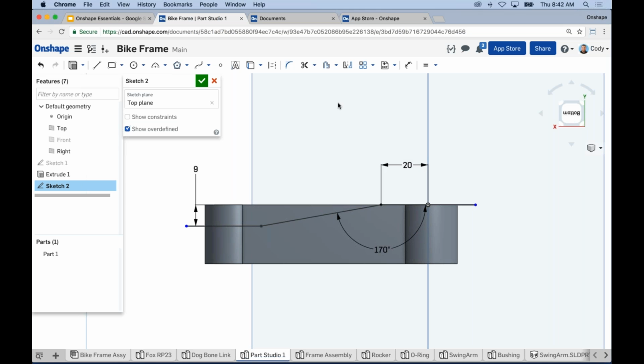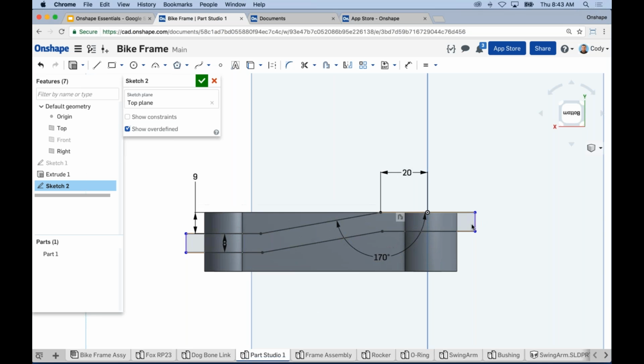And Onshape, of course, can do that. I have the offset command here. And I just left-click drag any one piece of this geometry and it will automatically grab everything attached to it. So if you're trying to offset dozens of lines and arcs at once, just left-click drag one piece of that chain of sketch entities and it will automatically grab everything in it. Right? So in this case, as I offset, I'll left-click, enter a value for my offset, in this case 8. Now I have an offset of those 3 lines. The thing I want to do next, of course, is close these ends up. And what I want to do is attach these ends to the edges of the model.